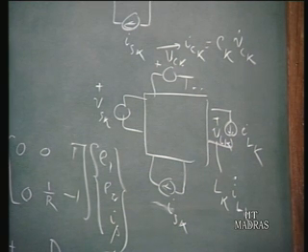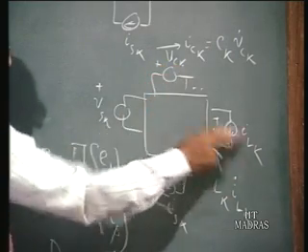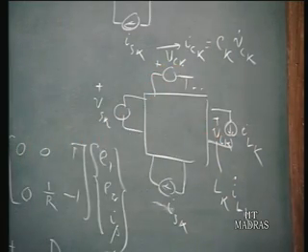In the same fashion, in the same network, you can express the output quantities that you are interested in in terms of VSK, ISK, VCK and ILK, which are the state variables. So in analyzing this, you can already find the equations for the output quantities in terms of the state variables and the input quantities. So we have on one hand the state equation and then also the output equation.